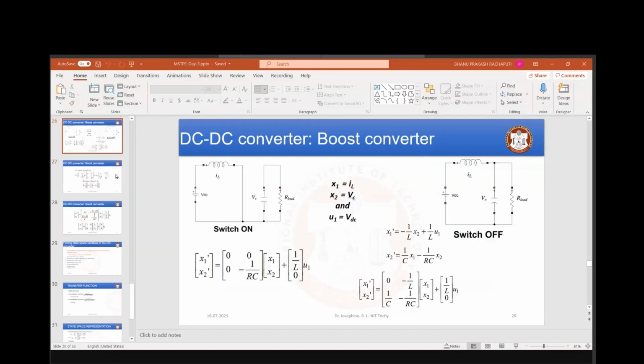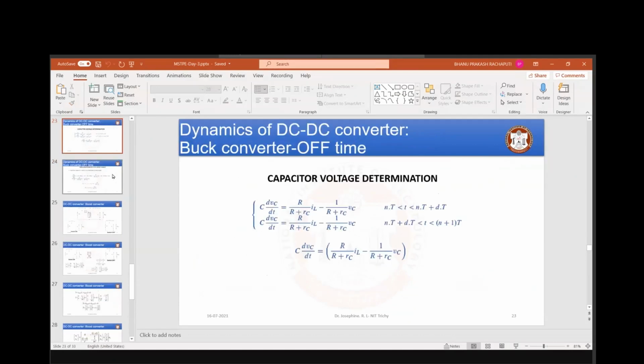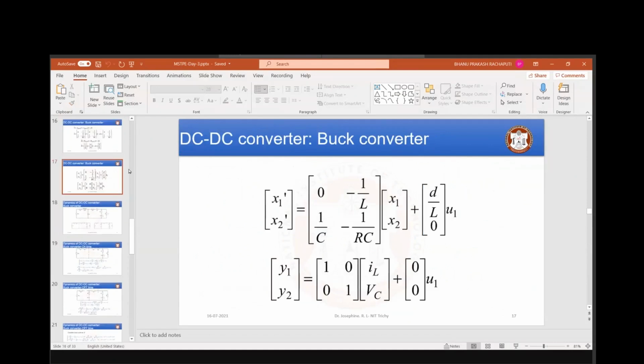See, when can you say that the state space is not nonlinear. Here x dot is equal to Ax plus Bu. Suppose instead of just x, I get a product of x1 and x2, then it is nonlinear, right? Here I've got individual forms, x1 separately, x2 separately.